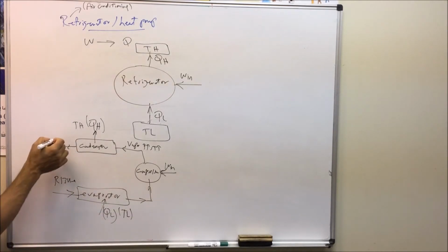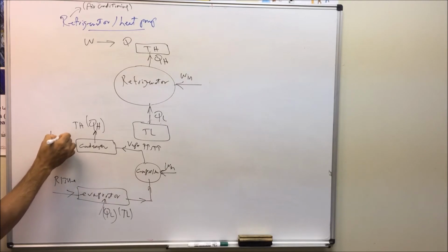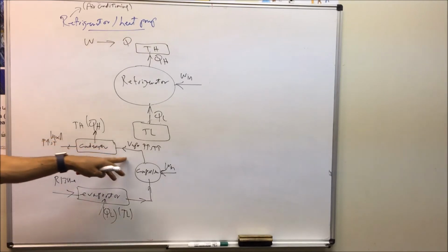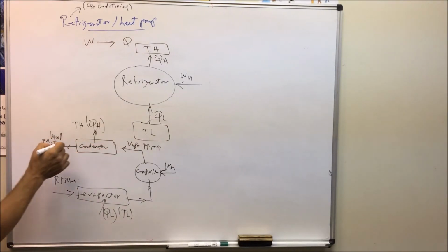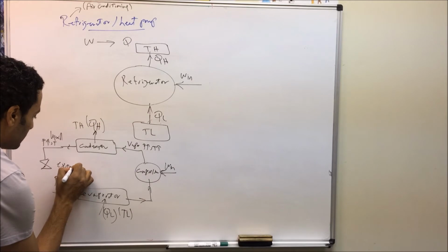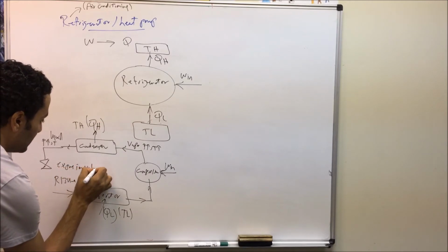In this case the Freon will be converted back, most probably to liquid. It is still at high pressure and its temperature is still a little high, but it has been converted from the vapor state to the liquid state. Then we pass this Freon through the capillary tube, or expansion valve, or throttling valve.